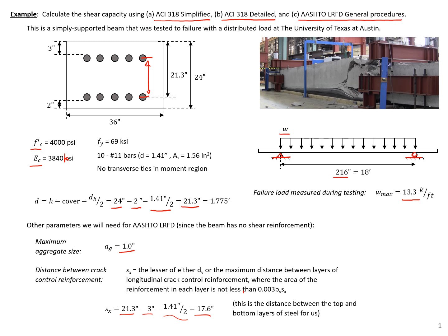If we had other layers of steel in between, so in a beam where you have other layers of steel going up and down your cross section, that distance is just between those layers of crack control reinforcement in the side.